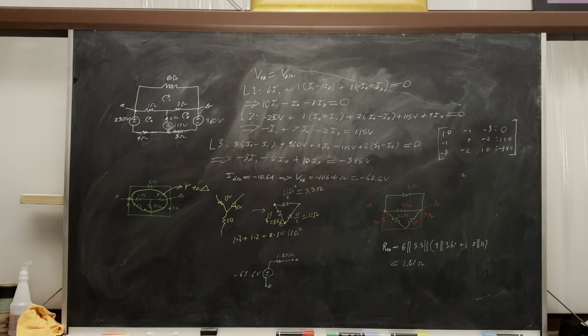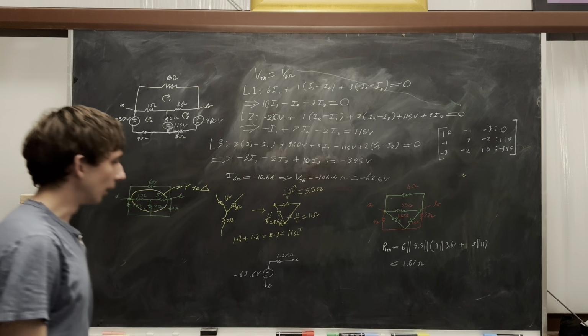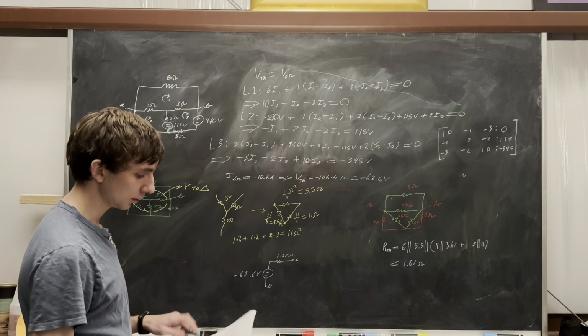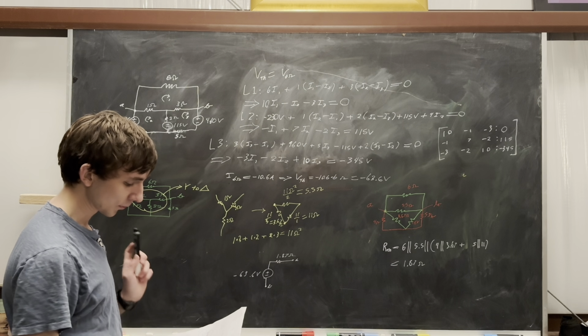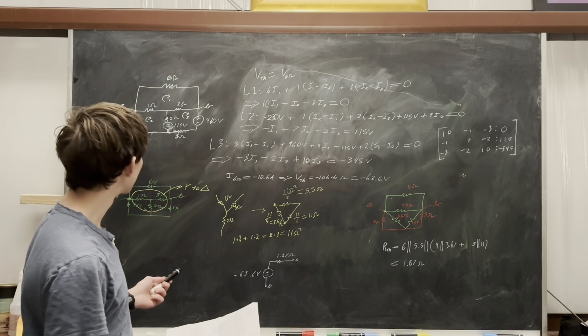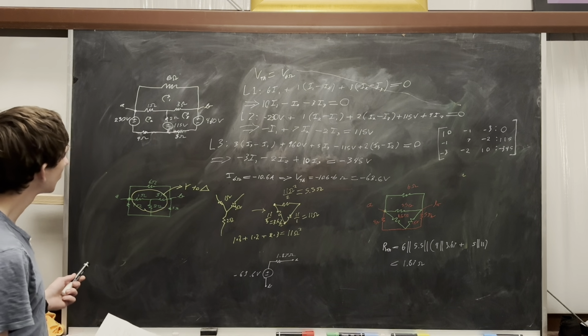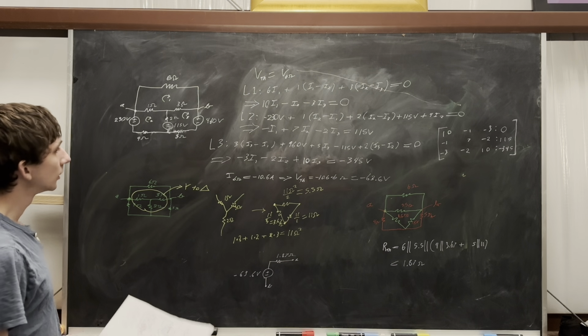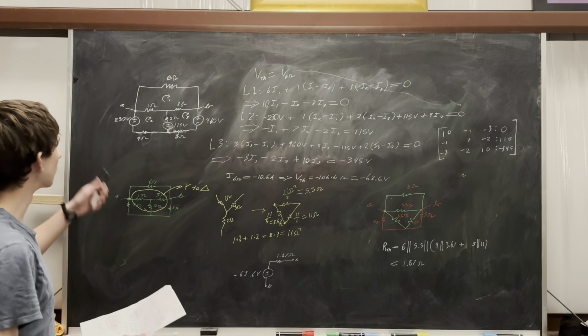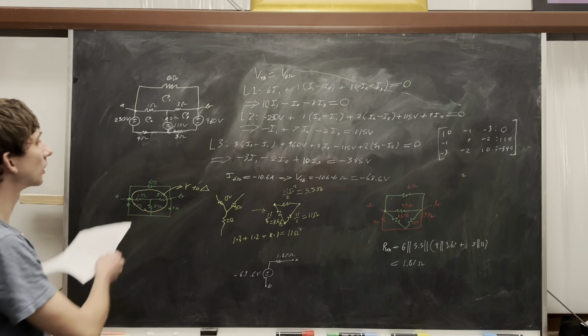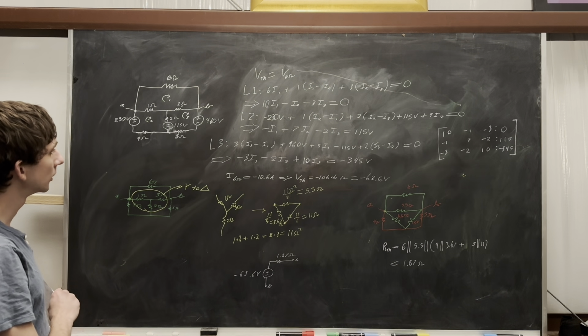You can see when we have just independent sources and resistors, this process is kind of tedious at best. I tried to do this using just source transformations, and it gets much more complicated. So yeah, for some of these, just shorting out your sources is easier than for others. Finding the short circuit current may be simpler.